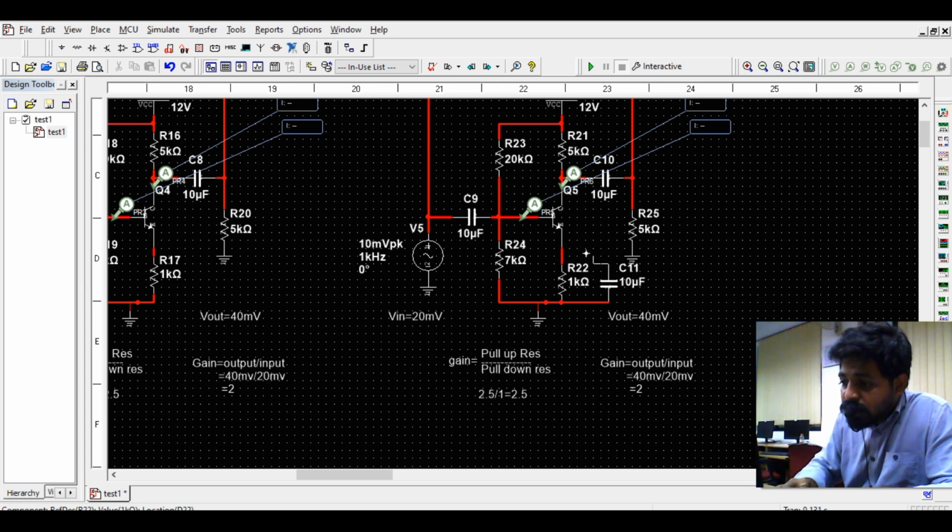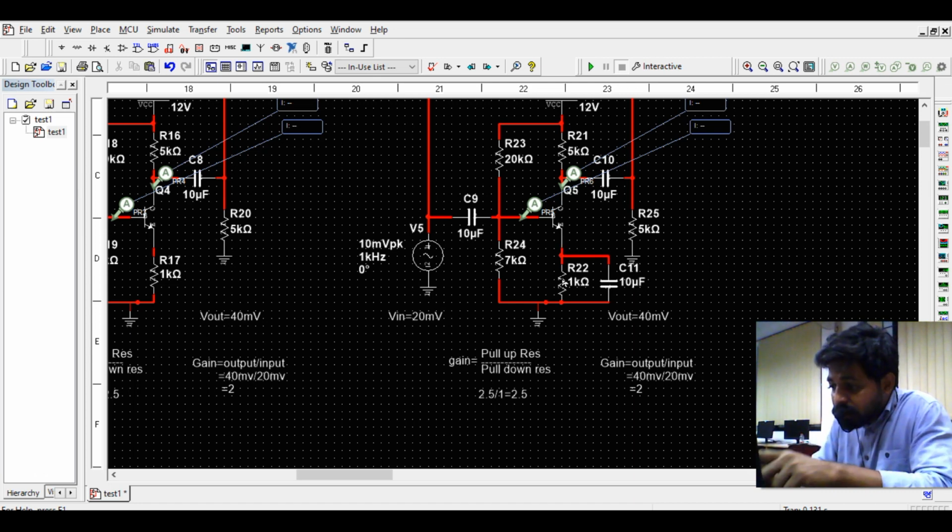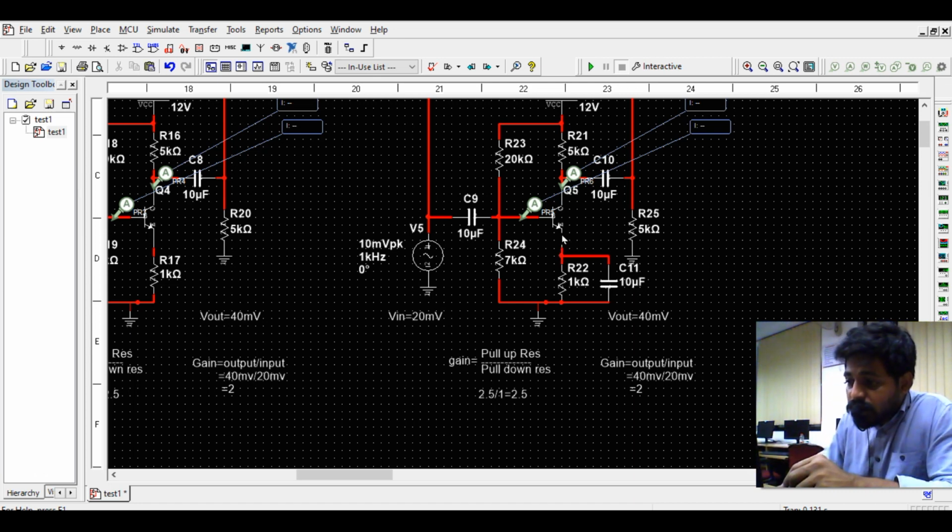So whatever the signal, whatever the current it passes to the resistor, right, now it is getting bypassed through this one. So the resistance will be totally bypassed. So the effective resistance across this branch is limited. The effective resistance across the pull down network is reduced. Obviously the denominator term is reduced. Obviously this term will be totally increased.